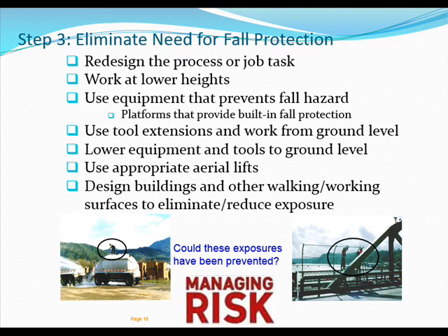Step 3. Eliminate the need for fall protection. Redesign the process or job task. Work at low heights. Use equipment that prevents fall hazards. Use tool extensions and work above ground level. Lower equipment and tools to ground level. Use appropriate aerial lifts. Design buildings and other walking/working surfaces to eliminate or reduce exposure.